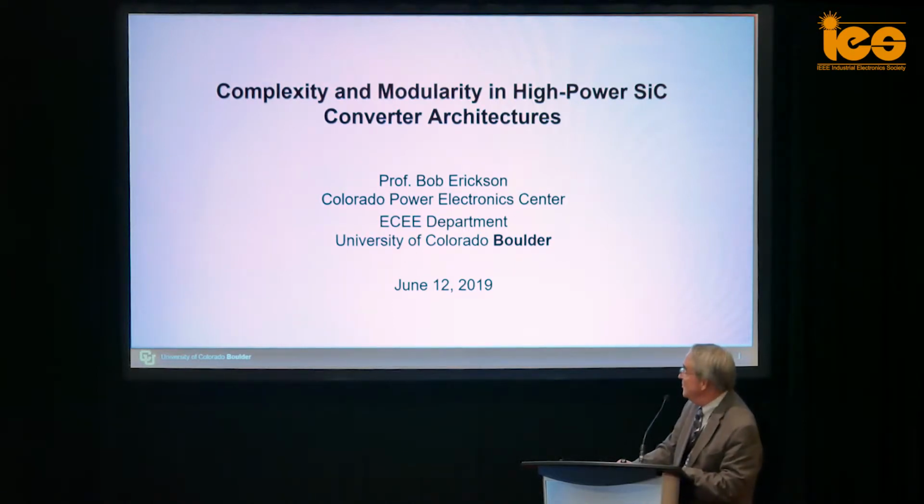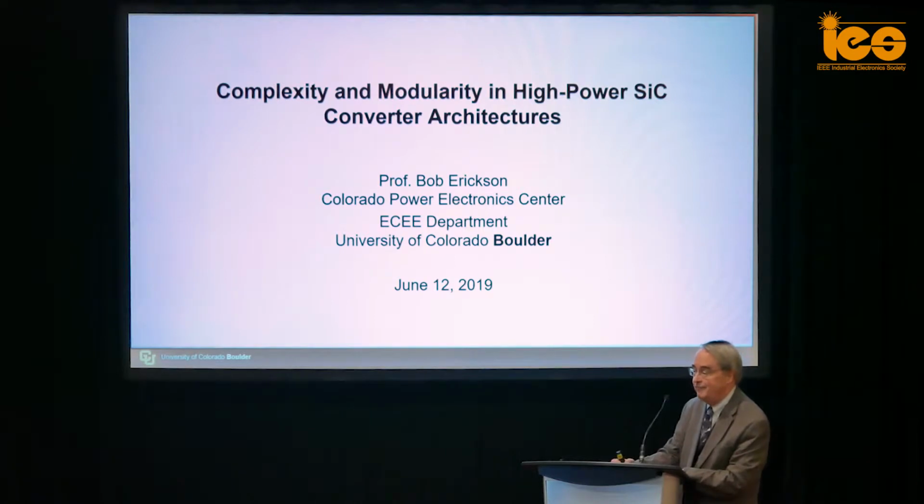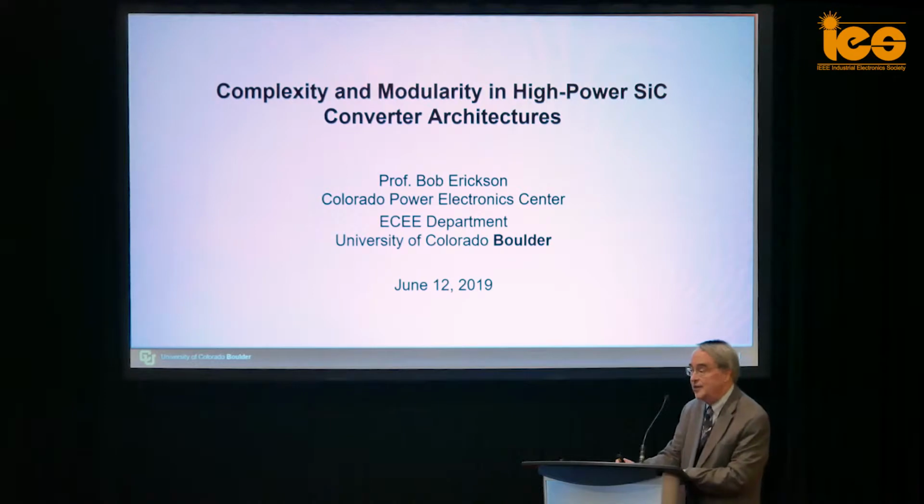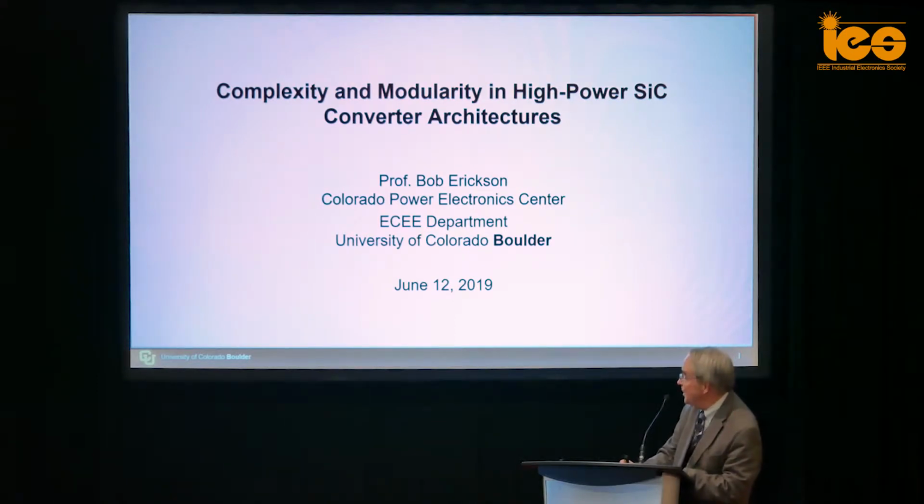But the problem is that those transistors are built in modules, and in fact, the module of the big transistor is a lot of small transistors connected together inside the module. So it's a brute force approach, and I'm going to present today that you can take those devices and connect them with better circuit topology and get not just an incremental improvement, but a really significant, transformational improvement in the converter performance.